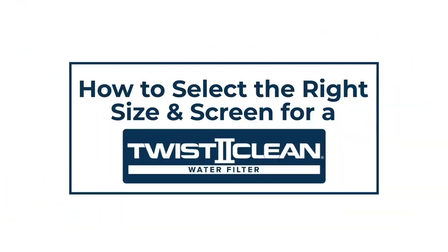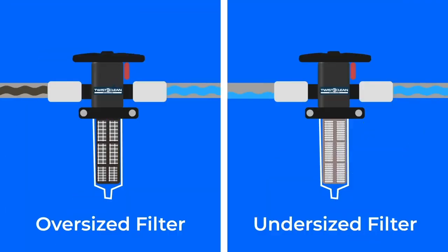When it comes to choosing a screen filter, there are several things you need to know about your water system to ensure that you select the right filter and screen size. You don't want to oversize or undersize your filter, as this means you may have to flush the filter more often and cause the system to inefficiently filter the sediment and debris, resulting in unclean water.